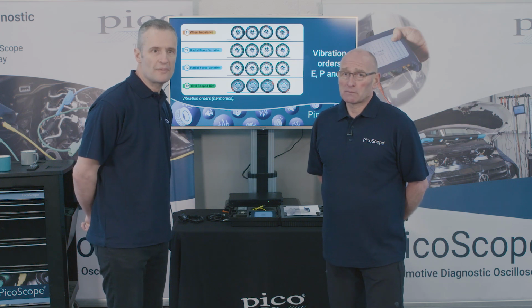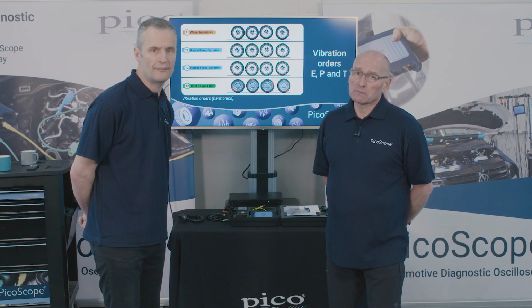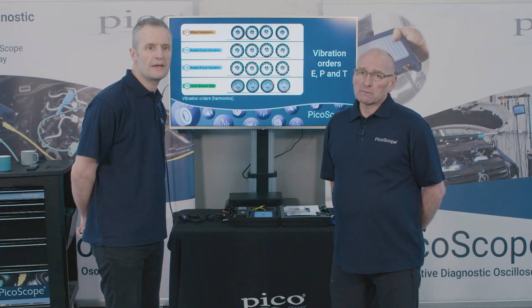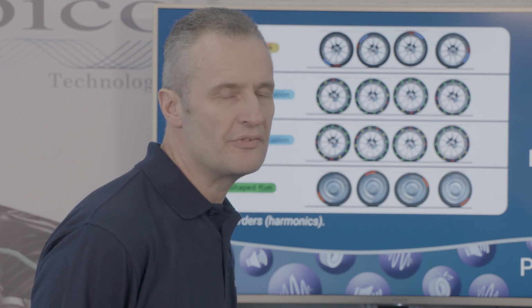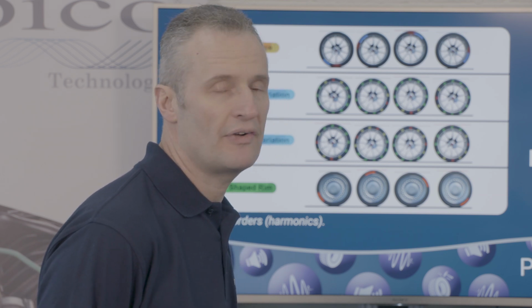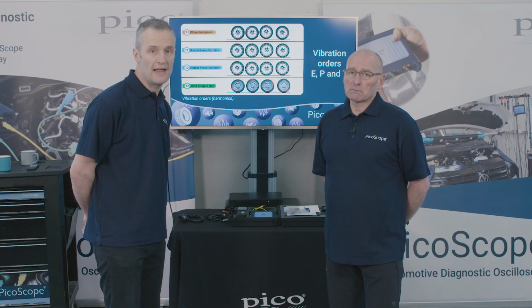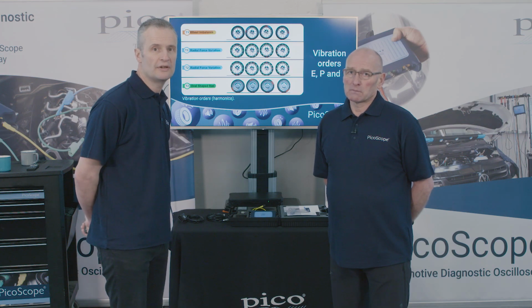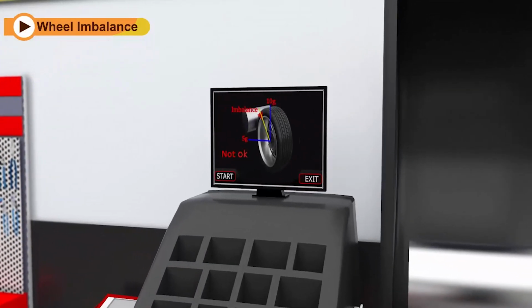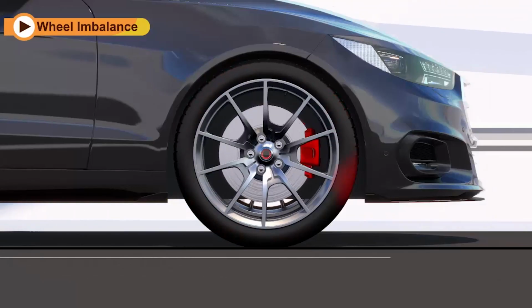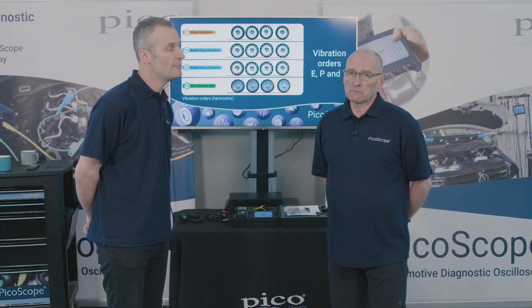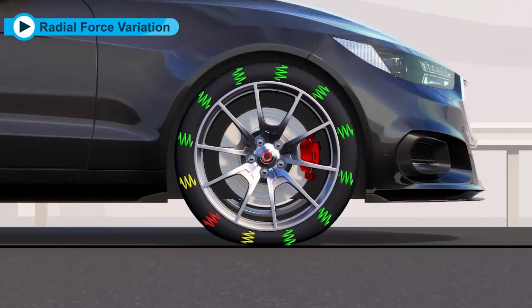That's where, once the vehicle has come in for its first set of tyres, rim replacement, whatever it may be, running the radial force variation balancing on those rims will minimise the risk of any vibration, first order or second order, by, as you said, Frank, phase matching the tyre to the rim. There is an allowance within the rim for deformation, and there is, of course, a tolerance in the tyre, and if we can match those accordingly, we can, again, minimise the risk. That's what that's about.